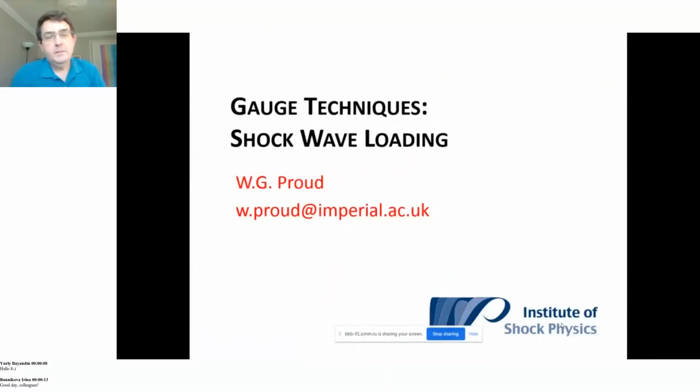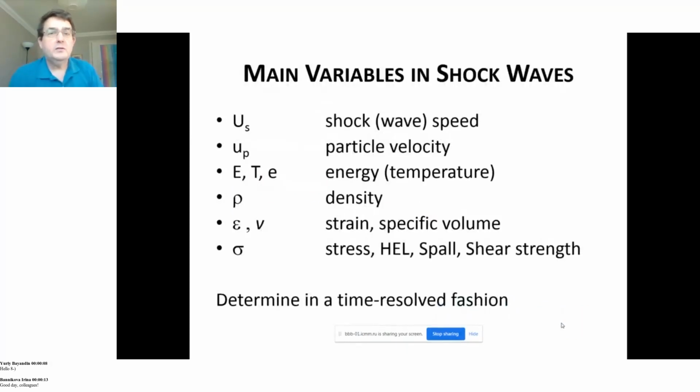So in the first presentation, I talked about waves and wave transmission being a very important factor, and that there were elastic waves and plastic waves. When we get onto the case of shock waves, we have a situation where the impact load is putting so much energy into the material, it causes a severe compression.